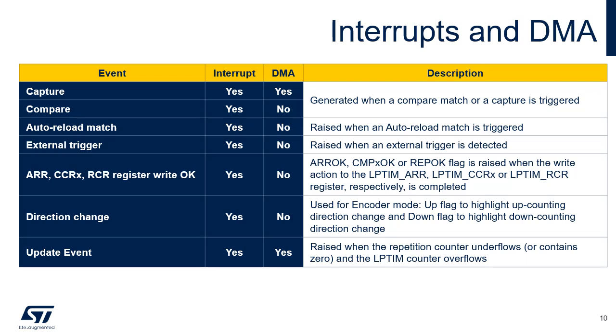These 3 interrupts are useful in mitigating the overhead of polling on the status or writing to these registers when the peripheral core clock is much slower than the APB interface clock.